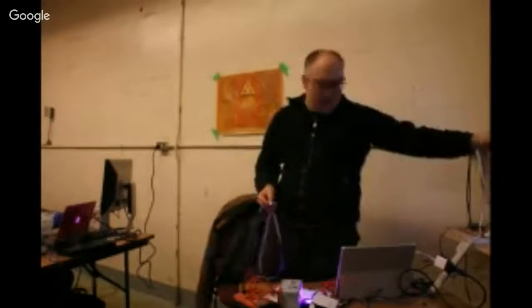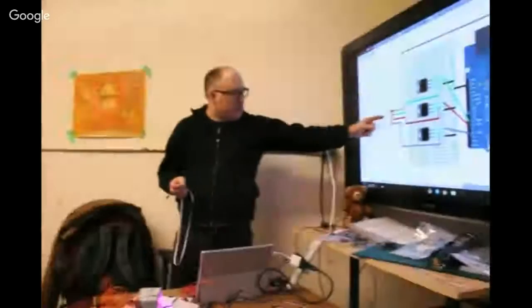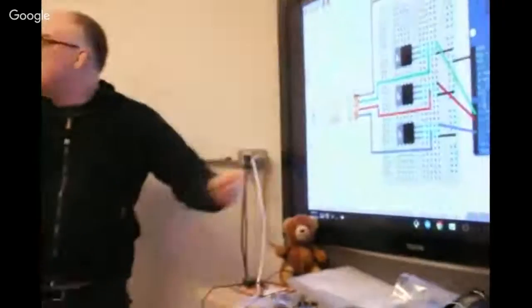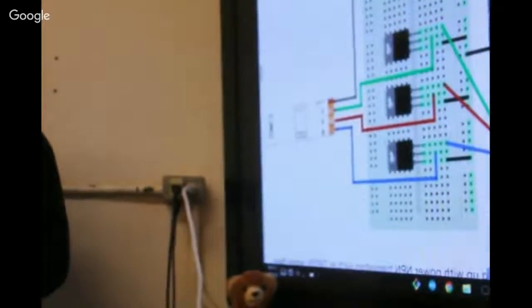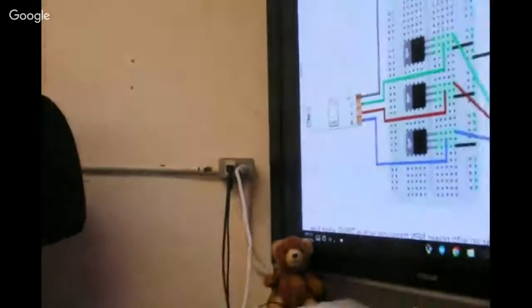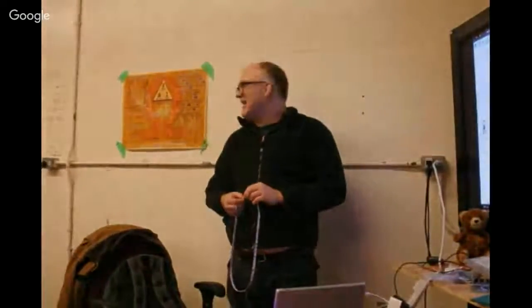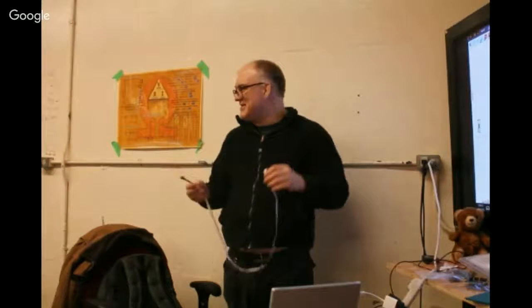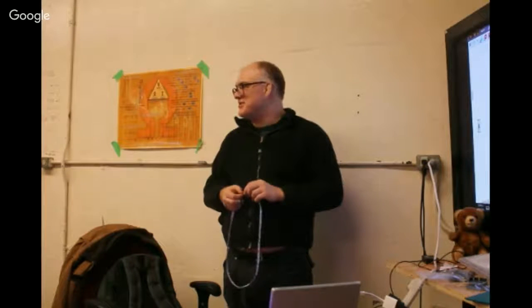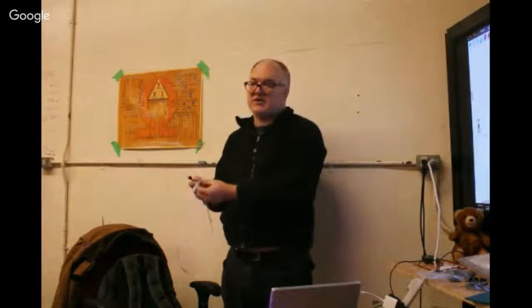The circuit we're going to wire up, you can see on the LED strips that we have a plus 12, G, R, and a B. These are analog LED strips. If we've gotten the Adafruit order in tonight, Mark, I think you got a bunch of the digital LEDs, which are infinitely cooler in some ways. They cost more and hook up differently. You can't use them in a high power circuit quite as easily. Yes, they have some disadvantages, but you can individually control the LEDs, whereas with this strip, the whole strip is doing the same thing at once because it is an analog strip.